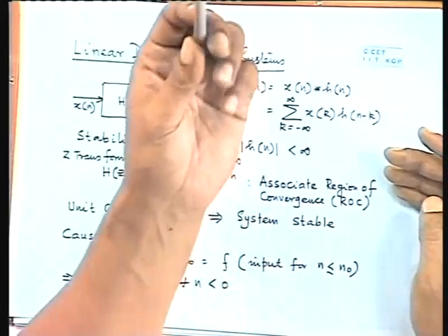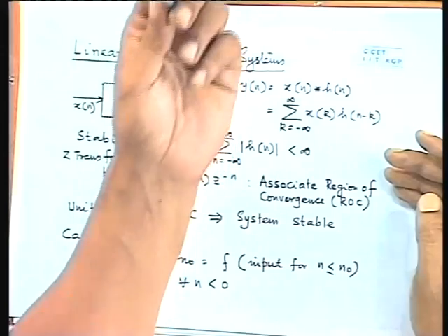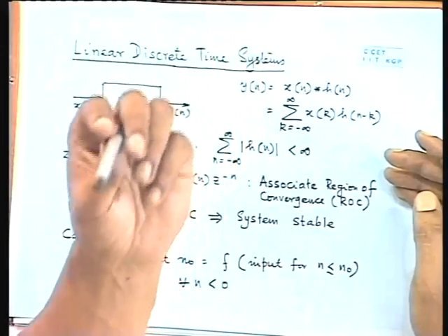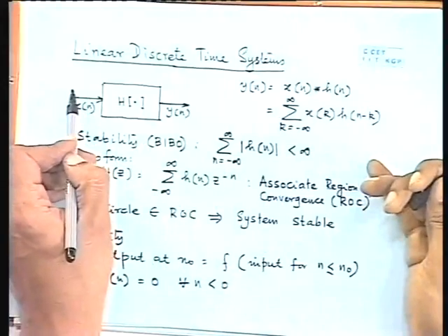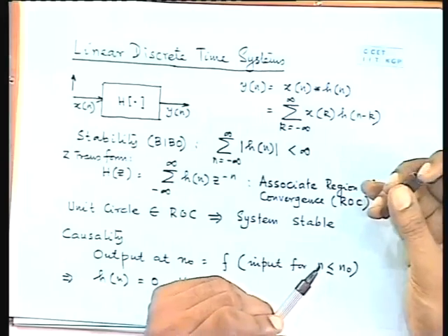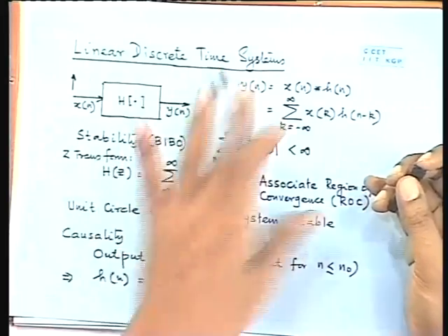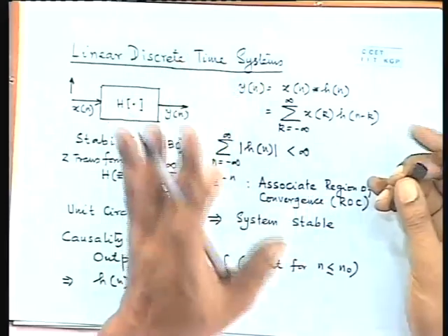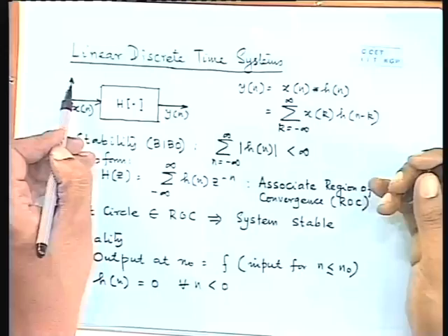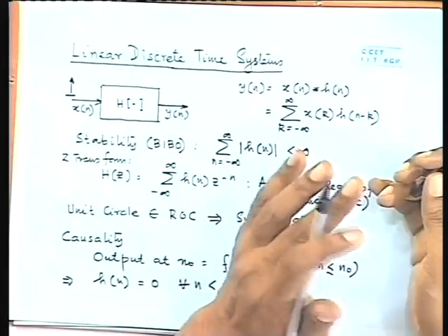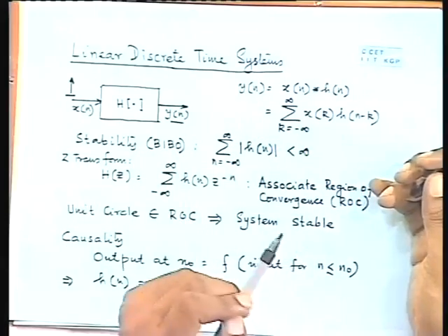Impulse response sequence is what you get if you feed an impulse to the system. In other words, if you feed a discrete time impulse, when we talk about impulses, once we have come down to the discrete domain, we always talk about a discrete time impulse. Discrete time impulse means one of them is a 1 and the others are 0. Then in general you will get a sequence of y.